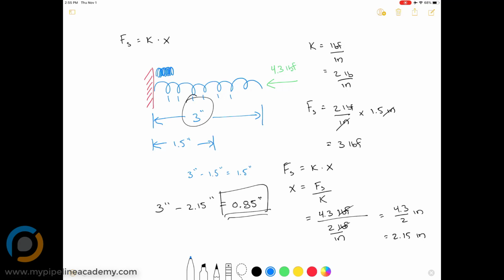If you fully compress a spring, it can plastically deform, or it may just reduce the life of the spring, so that instead of holding up for 1,000,000 cycles, maybe it holds up for only 20,000 cycles before it starts plastically deforming or losing its nominal spring characteristics. So anyway, that is how to use the spring force formula.